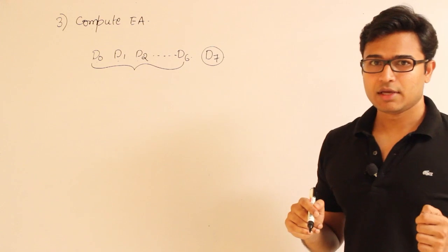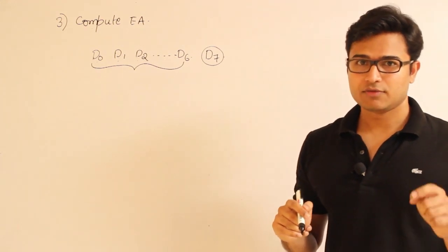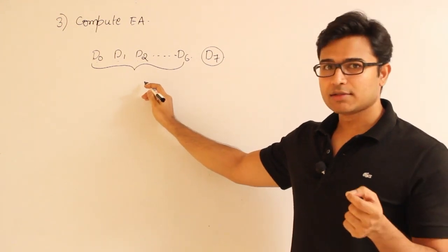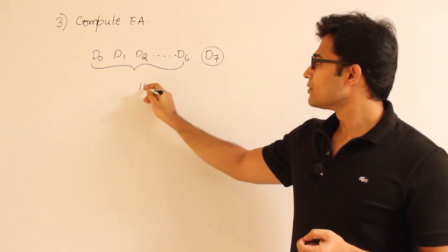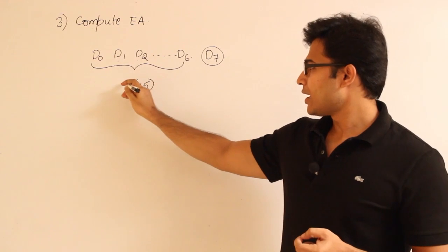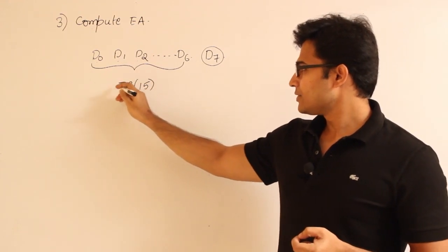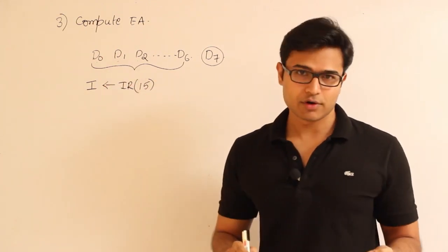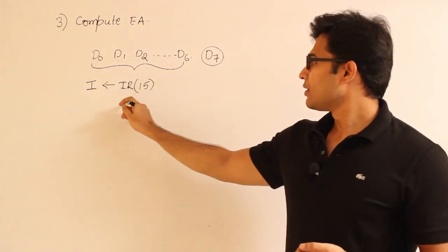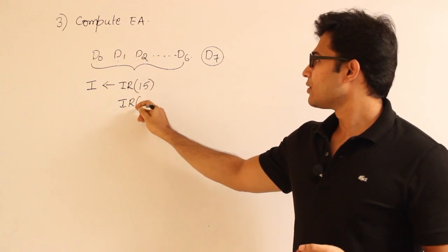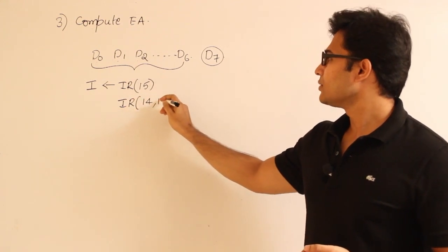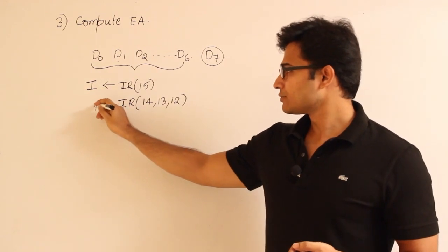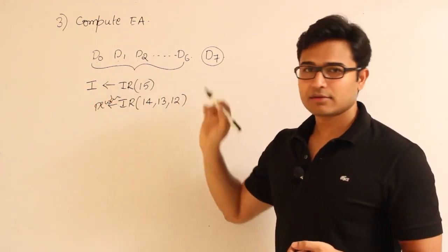So if you remember, while decoding the instruction, we did three things. We sent the 15th bit of the IR to the I flag, which says the mode, and then IR bits 14, 13, 12 are sent to the decoder, isn't it?